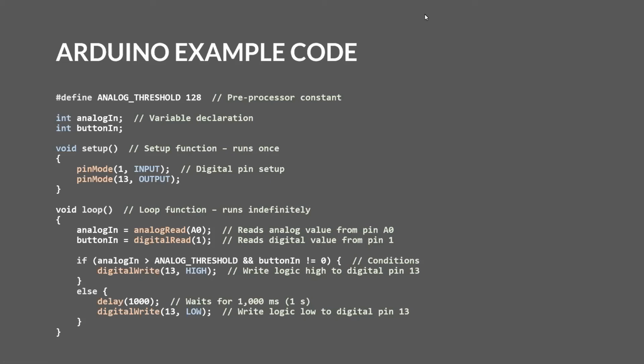I believe in some devices you might have a pin which is shared between an analog to digital converter and a digital to analog converter. I'm not quite sure how Arduino deals with this, and I've not really come across any Arduinos that have that feature. But in general, if you're doing an analog read, you won't need to set the direction of the input because it's automatically inferred.